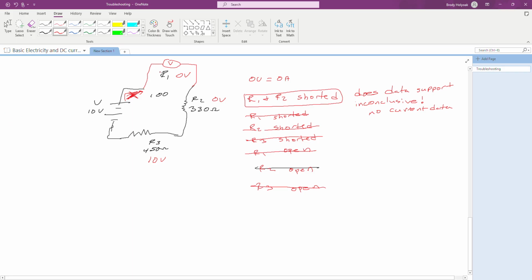So when we make this connection, if there's no connection point here and we plug that meter in, all of a sudden all the current is going to go through this meter and back out, which means we just made a complete circuit. So now there's current flow through everything.